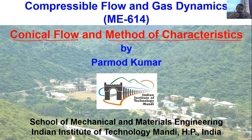So what we do is take the help of the method of characteristics, because it gives us a kind of grid, a characteristic network, along which our governing equations become the compatibility equations, and these compatibility equations are mostly in the form of ordinary differential equations, so their numerical solution is actually quite easy.